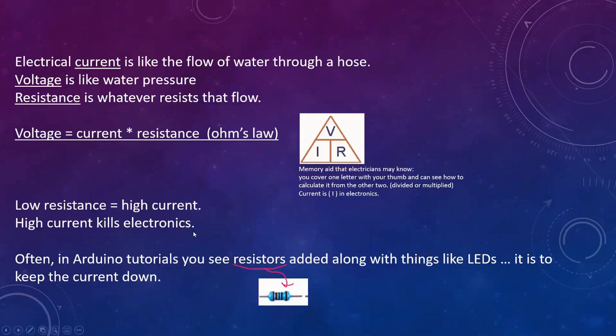That's it. And so oftentimes in Arduino tutorials, you'll see resistors, which are these components with those stripes on them. You have about 100,000 that came in your kit. You'll see resistors added in various circuits. The purpose of those resistors is just to keep the current down so that you don't damage your fancy electronics. These resistors also come in different flavors. They're labeled by how much they resist electricity, so higher numbers are more resistive. They go from, I think, one of the lower ones is 220 ohms, ohms being the unit of resistance, all the way up to, I think, 100 kilo ohms.